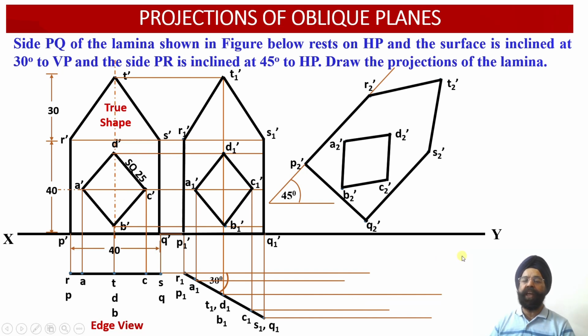So let us evaluate each one of these 9 points into the plan projection view. So first of all, we have drawn the horizontal projectors through these 9 points of the previous plan projection view. Now one by one we are going to draw the vertical projectors from each one of the elevation projection view and find out the corresponding points of intersection, right?